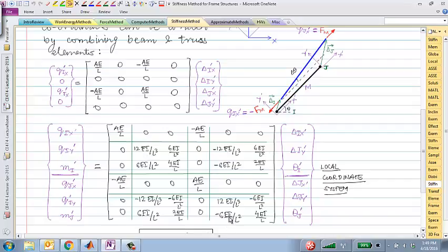So all we did last time was to combine them both to get a measure of the 6 degrees of freedom per node, because each node has 3 degrees of freedom, to 4 forces and 2 nodal moments. So this relationship, as I mentioned last time, is equivalent to the relationship for the trusses, or the 4x4 relationship for the beams that we have developed.